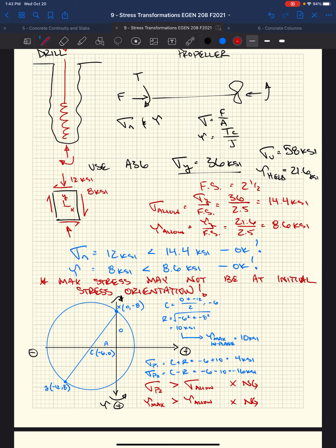But we just went through a huge exercise on Mohr's circle and stress. In tensile testing, we have the modulus of elasticity, which is the slope of our linear elastic line. Stress is related to strain based on that modulus of elasticity. So in order to have stress, we have to have strain, deformation. You can go through a whole exercise of a Mohr's circle geared towards strains, so we can transform strains at any given cross-section and orientation of the same block.